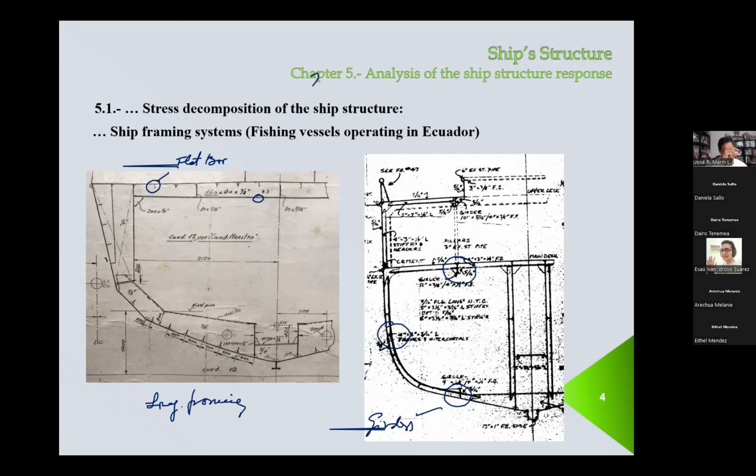12 millimeters is a very thick plate. Does that make sense? If you go and visit, you say, okay, this is a 100-meter long ship, and in the bottom they have 11 millimeters. They start making some sense. So you have a 60-meter long ship. I wouldn't expect to have 12 millimeters.